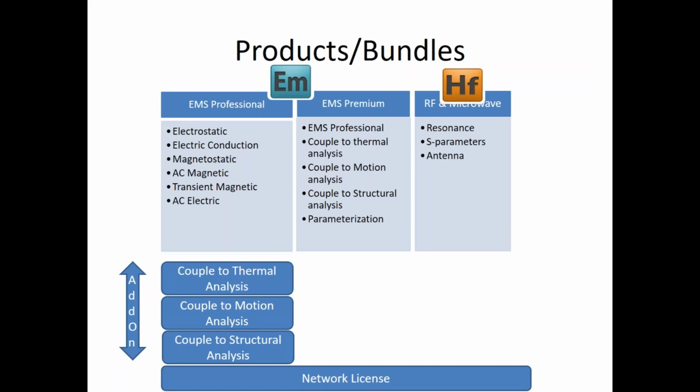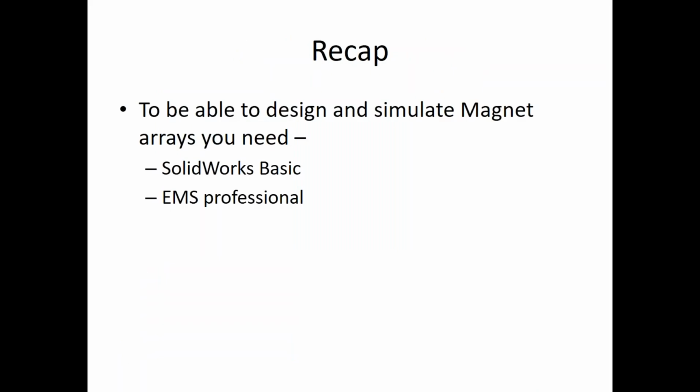As far as HFWorks, this product is concerned, there's just one product, and it has 3 different solvers, as you see. Now, just to recap, to be able to design and simulate magnet arrays that I showed you, what do you need? You need, in this case, SolidWorks Basic, or if you have EMS Inventor or SpaceClaim, any of these would work fine. And then you would need EMS Professional as the product.